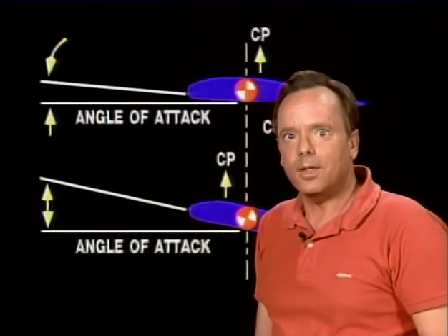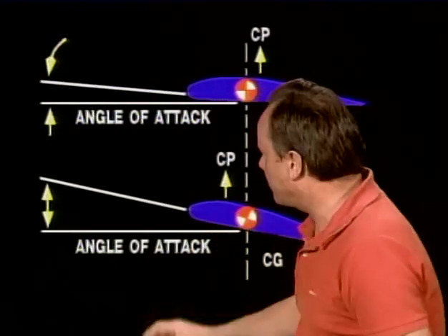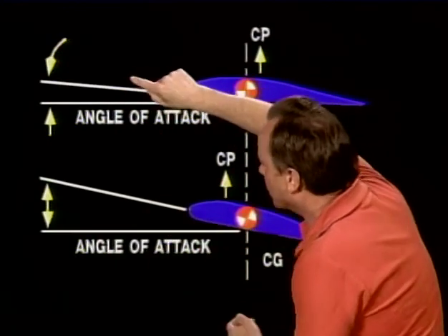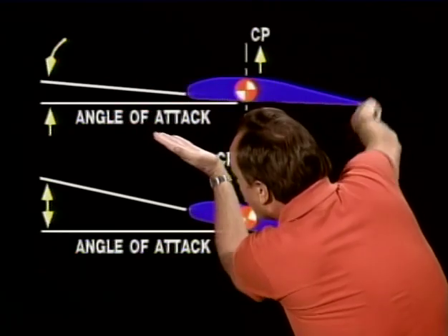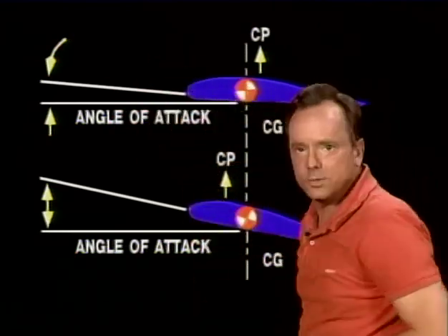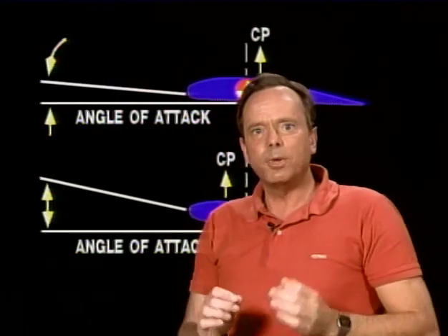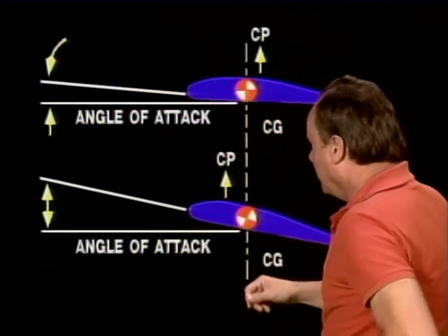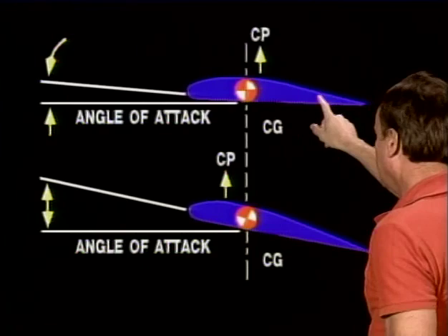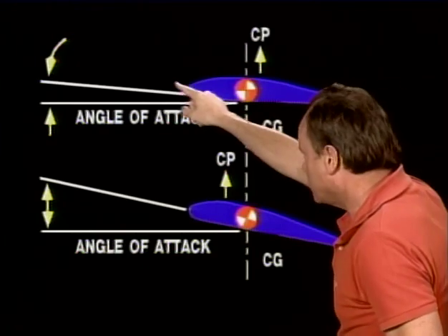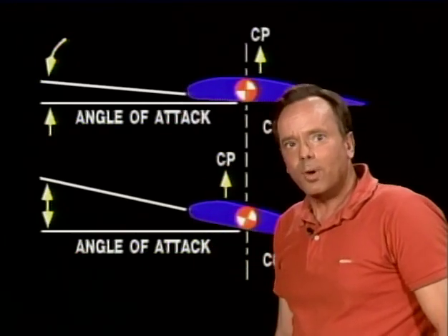They're going to say to you that the angle of attack is the acute angle. That means a small angle. In other words, here's the small angle; going all the way around the other way would be the big angle, so the small angle is the acute angle. And it's the angle between the chord line of the wing, and in this particular case, that's a line drawn from the trailing edge of the wing to the leading edge of the wing. That'd be the chord line of the wing to the relative wind.